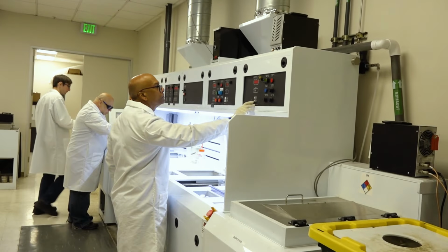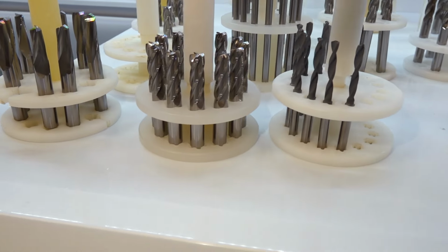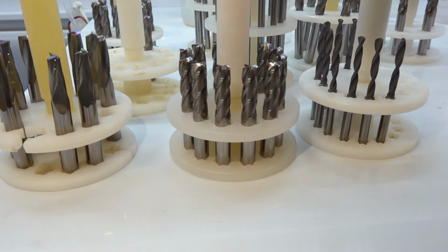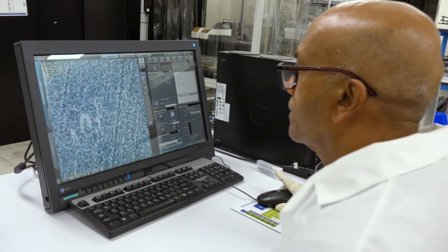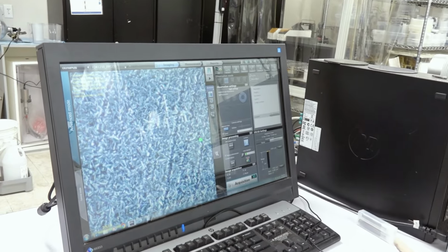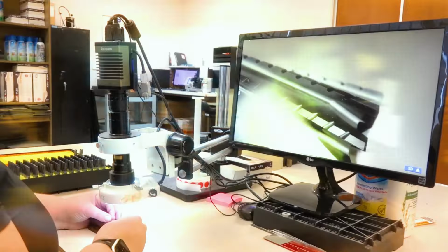Well, there's a lot of applications where diamond can improve a product. Diamond is known as a super material. A lot of people know it's the hardest material there is, but it has a lot of other extreme properties. It's also the stiffest material. It has extreme wear resistance. It's extremely resistant to chemical attack and etching. It has the highest thermal conductivity of any material. It makes a great heat sink. And so there's a very large number of properties that makes diamond very special.